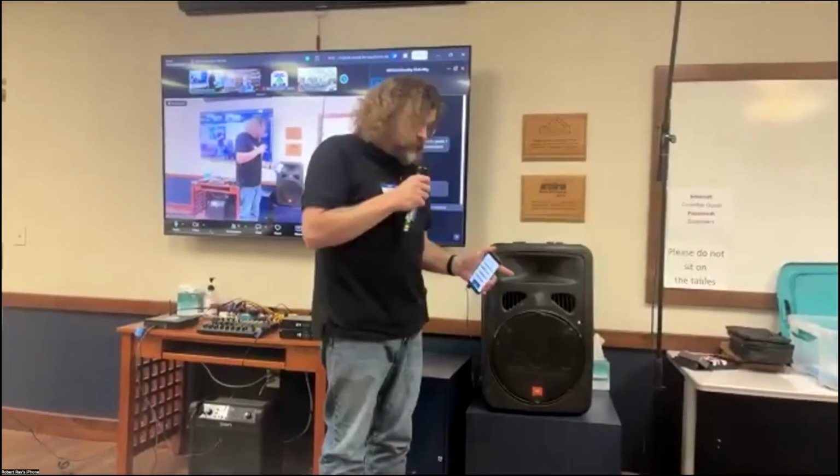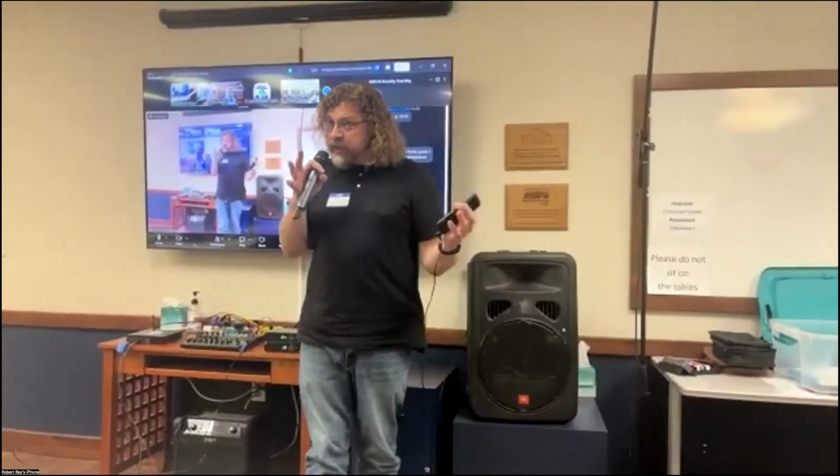3K, that's wrong. I didn't say the human voice, I said human speech, and speech includes more than just your vocal cords. It includes your teeth and your tongue, S's and T's that don't involve your vocal cords. S's and T's have higher frequencies than just 3 kilohertz. So what they've done with this compression algorithm is they have used 6 kilohertz of input. So they're capturing 6 kilohertz worth of human speech instead of just 3 kilohertz. So that's why it sounds better in like the S's and T's.